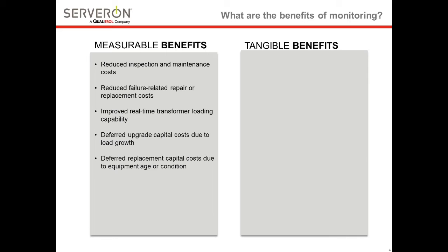Deferred upgrade capital costs due to load growth. So where transformers are starting to be overloaded, perhaps as load growth occurs, if you have monitoring, you can potentially defer upgrading that equipment by carefully monitoring as you increase the load.